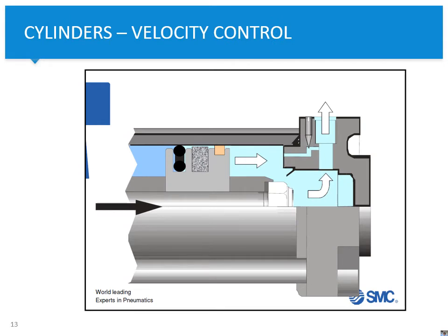One thing that is important, but I'm not going to really discuss in detail, is the amount of kinetic energy you want your cylinder cap to absorb. You can imagine that if there's a lot of velocity that it needs to be stopped at the end of a stroke. So in this way you can see the retracting stroke in which a piston over here is going to move back to the cap.